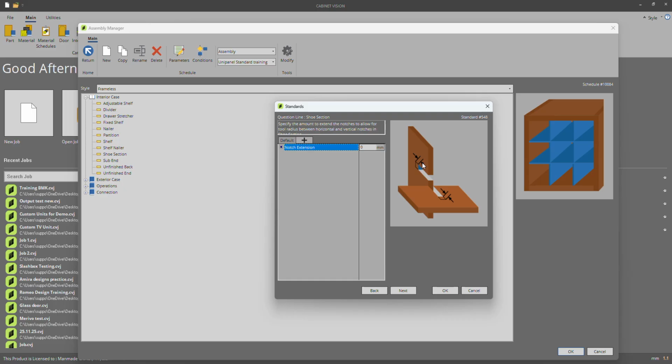So what would you say you'd add there? 10 mils, 5 mils? Normally we would use a 16 now, so 5 mil should be fine. On a 16 mil cutter, 5 mil should be fine. Sometimes you use bigger cutters, sometimes a smaller cutter to prevent support. It depends what tool you've got.